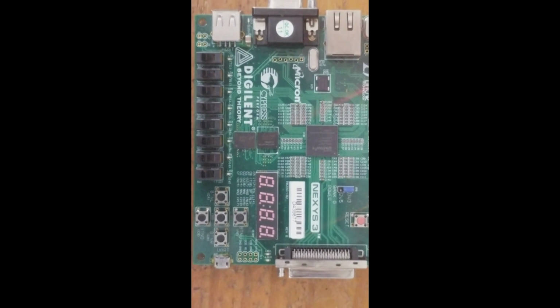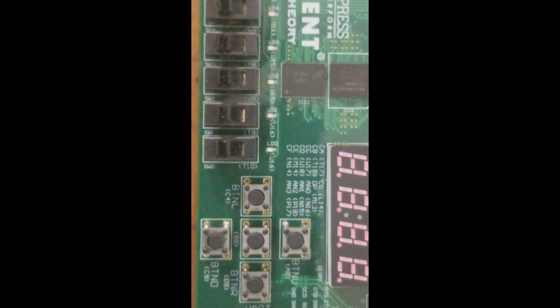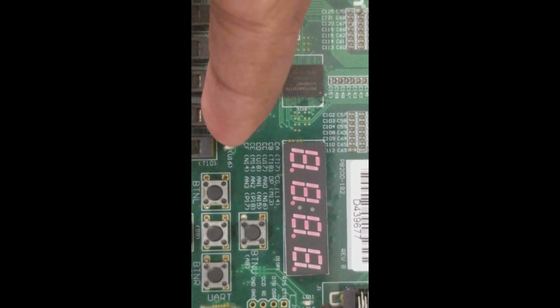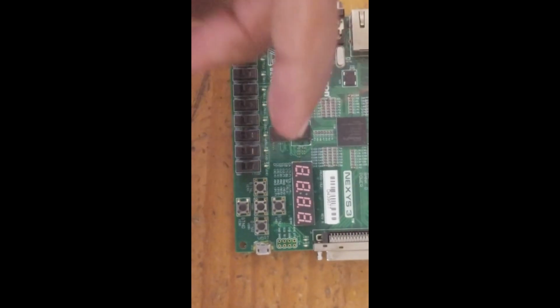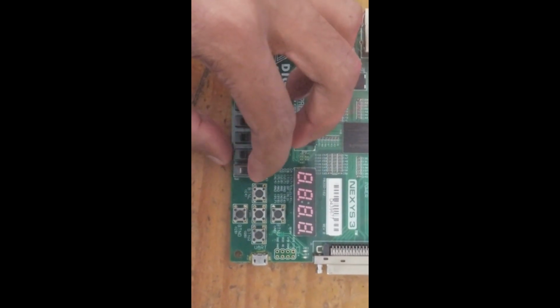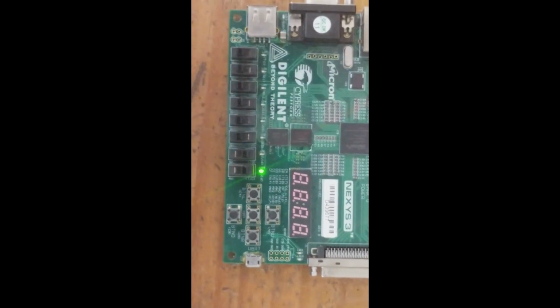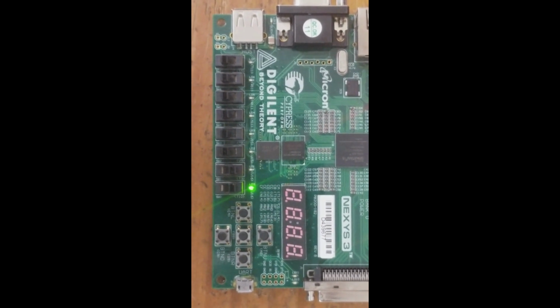All right, so this is the board. As you can see, we have the switches here that we programmed, T10, which is right there, and T9. So these are the inputs to the AND gate, and we have the LED that we are using, U16, that will light when both switches are on. So if we turn on this switch only, the LED should be off. If we turn on the other switch only, it should also be off. If we turn on both of them, the LED comes on. And that signals that our program is working.